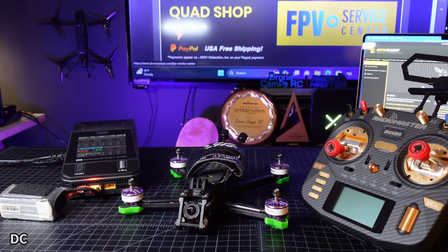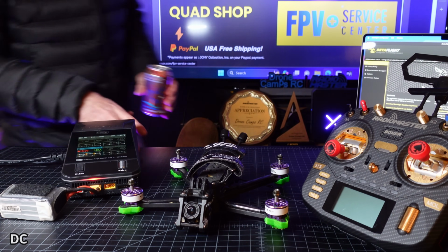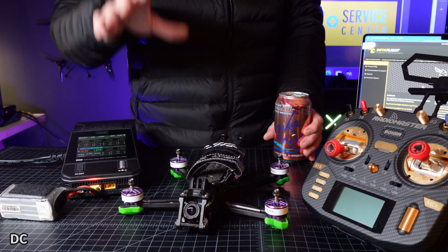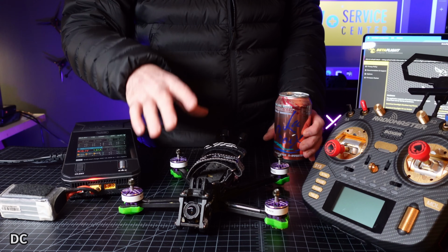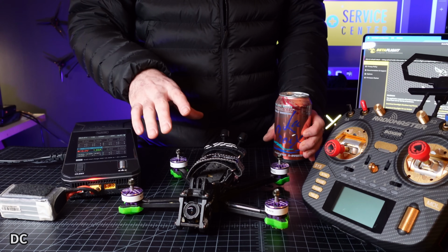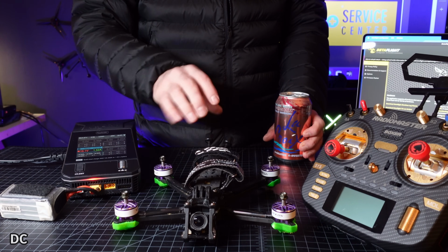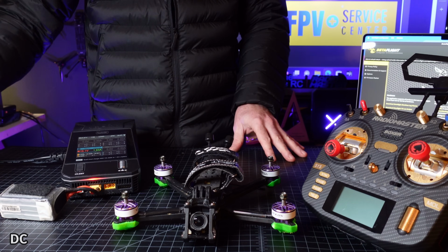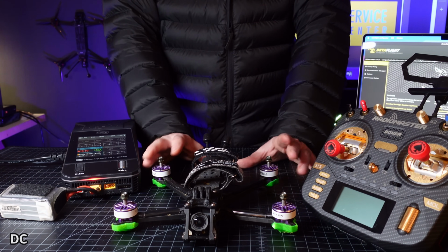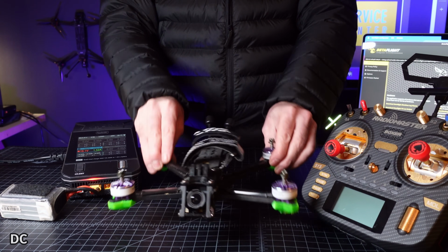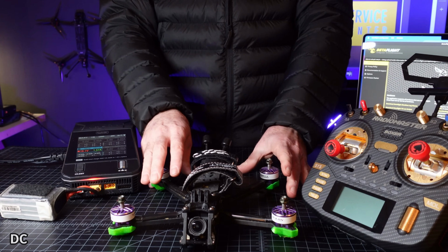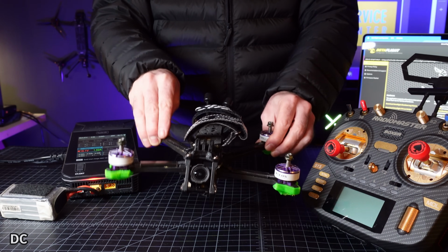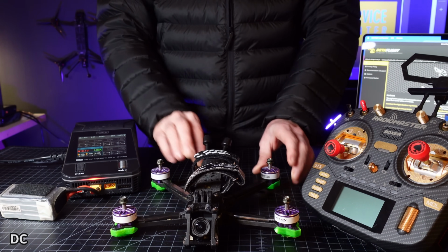Not exactly. So when you go out to fly for the first time, your first 5-inch, say you've already flown everything else, you're ready to go with this one, what you really need to do is stand about 10 feet, 15 feet behind it, give yourself some space, and keep it in angle mode, and that's stability mode. So it will have stability, but what you need to do first is line of sight fly it. Bring it up off the ground to make sure that it hovers, and then just simply bring it back down and land it.